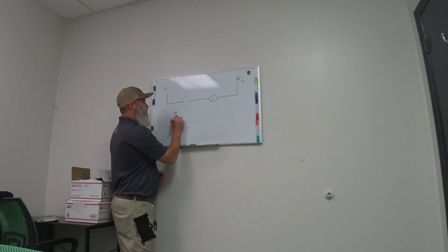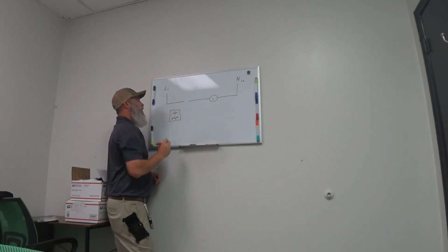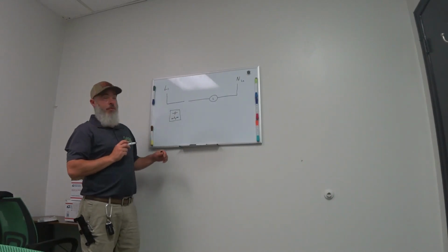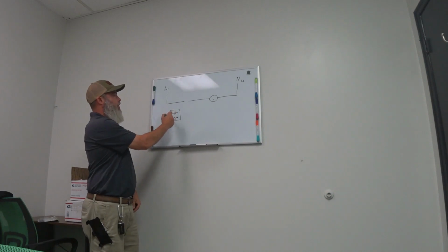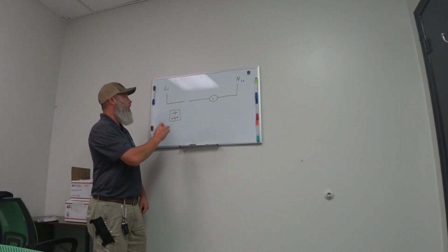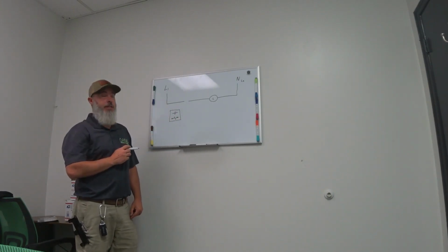Yep, got you. You've got a coil. So this is usually like this. So if you put 24 volts on that coil right there, it's going to close that switch, those contacts right there, in order to transmit power wherever it wants to transmit.